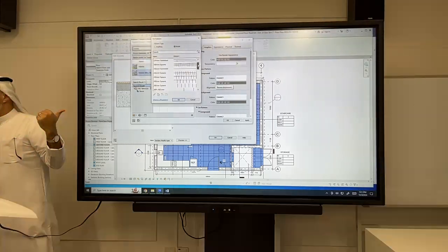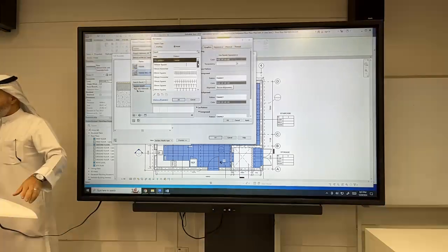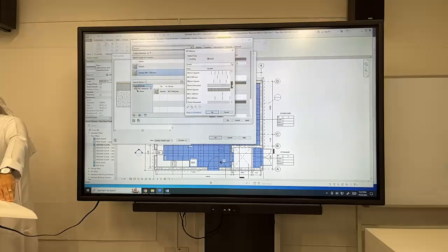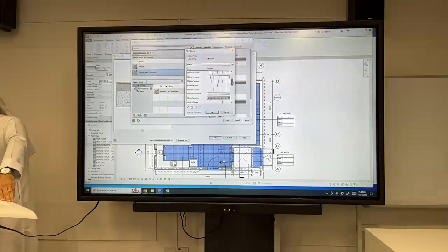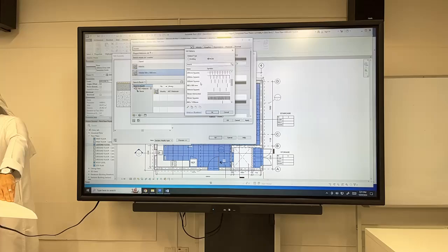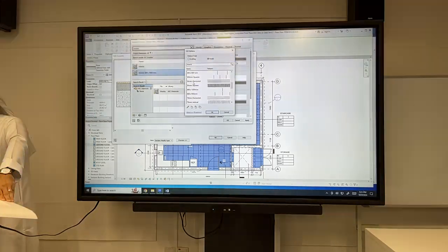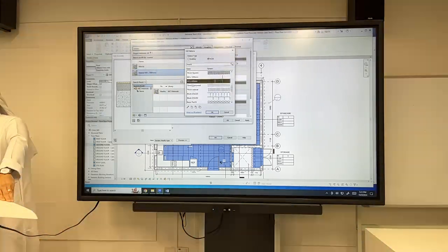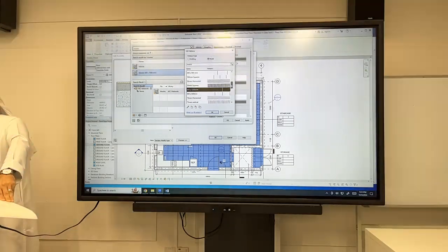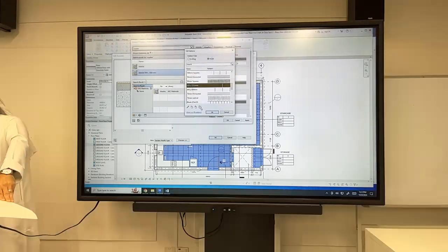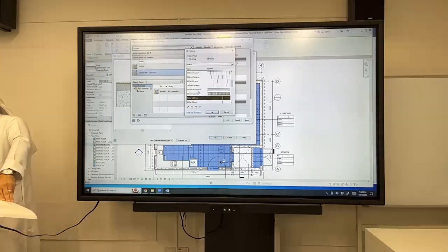and then this is where you change the size. Now we have different options already in the system. So if you're doing square tiles, we already have 300, and then a 250, and then a 200, and then a 100, and then a 600 by 600, so you don't duplicate those. 600 by 1200 is already there. I put 500 by 1000. So pick one of the rectangular ones, for example 600 by 1200. If it's rectangular. If it's square, choose one of the squares. It'll be easier to change.